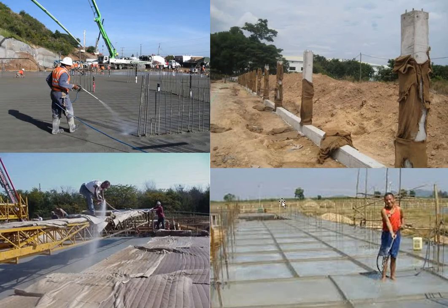This is another method of curing. You might have seen this at our badminton court in MEC. They have made ponding structures on the sides and then laid water over it for proper curing. Okay, and only after this 14 to 28 days of curing does the concrete completely attain its strength.